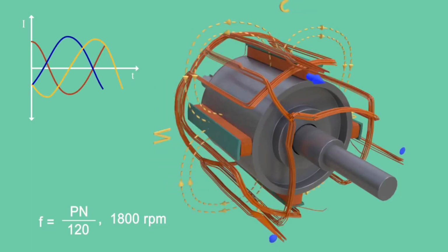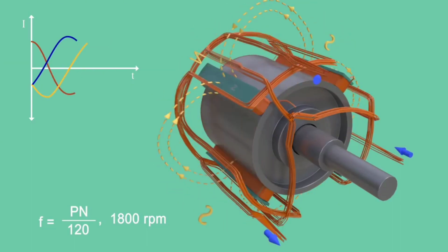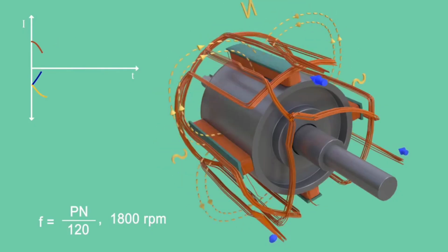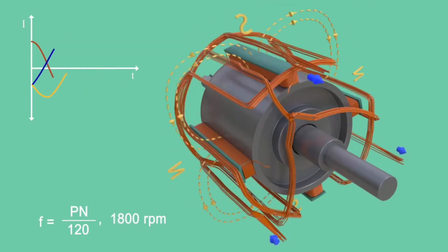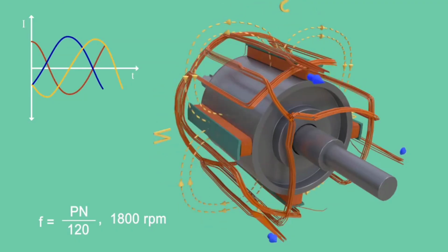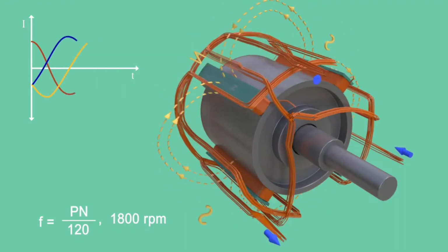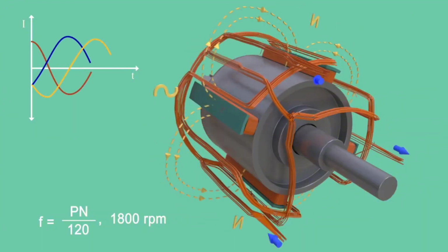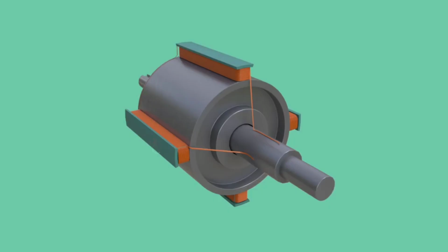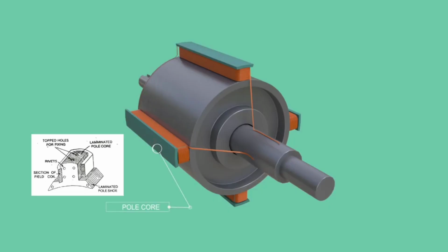So salient pole rotors are generally heavy, with 10 to 40 poles, which demands lower RPM. Salient pole rotors are used when the prime mover rotates at relatively lower speed from 120 to 400 RPM. Pole core is used to effectively transfer magnetic flux, and they are made with fairly thick steel lamina. Such insulated lamina reduces energy loss due to eddy current formation.